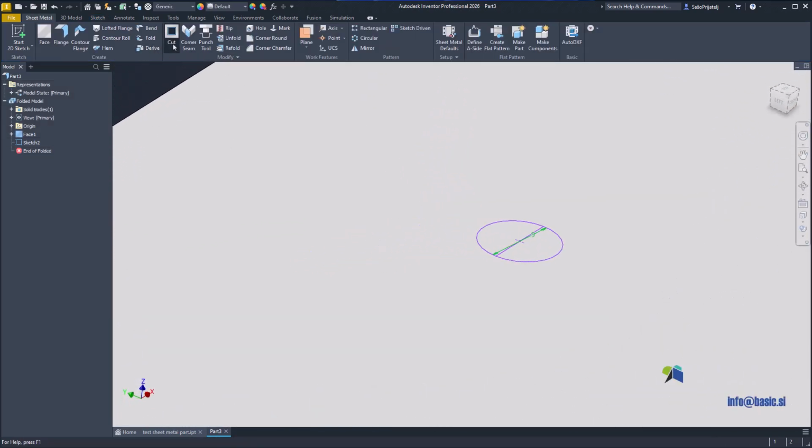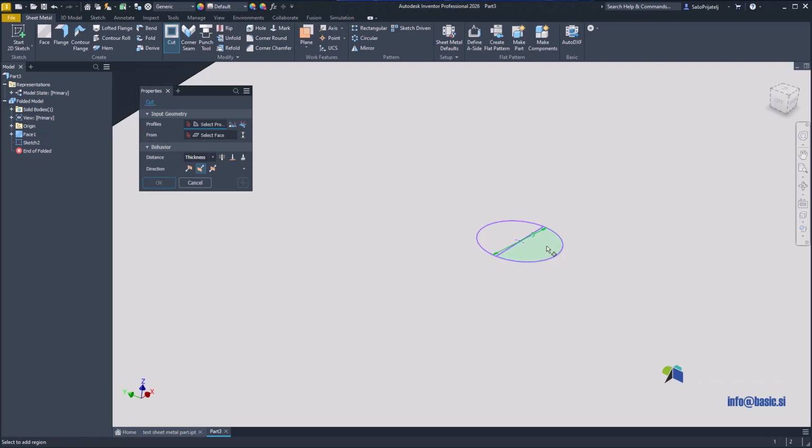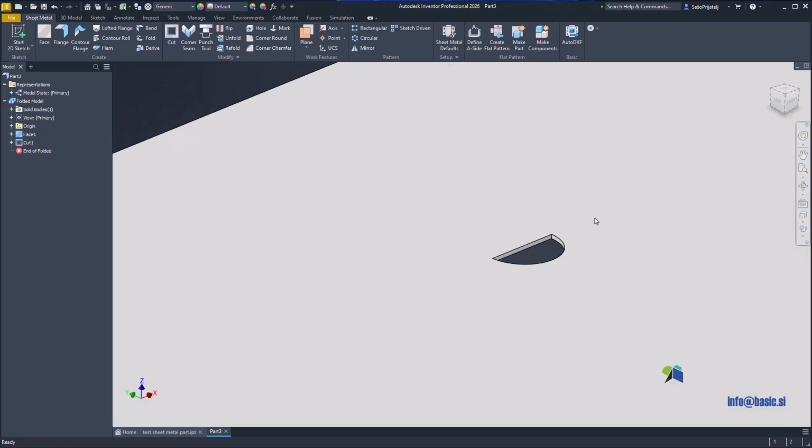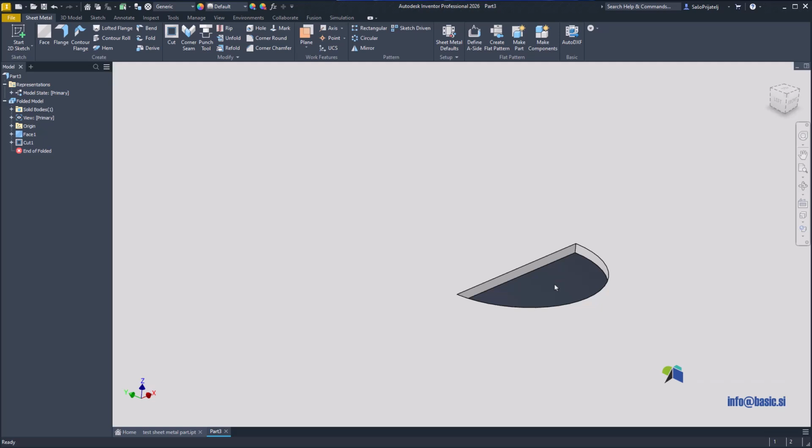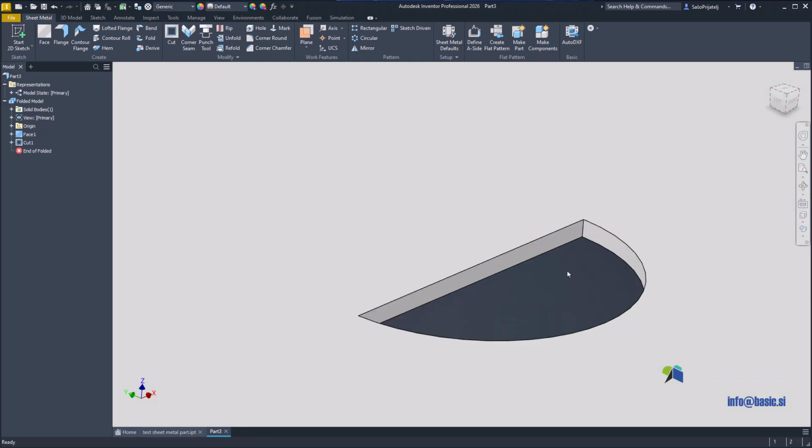Now create a cut and use the half of the circle. I'm doing this so that we can have only one reference geometry to position this. So in this case I want to limit this to the point we created on the first sketch. That's why we are going a bit around with this geometry creation. I created only half of the circle, so I get this face on which I can place a new sketch to create the missing geometry for the thread.